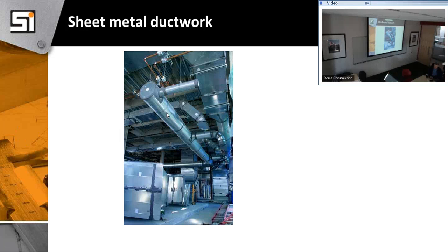The problem with rectangular duct is you get those real wide pieces of duct, and they want to waffle, so they create noise. They allow what I call breakout. Round duct is stiff, it doesn't break noise out. So if I ever went through a real noise-sensitive area, I'll use round duct because it won't allow the noise breakout. It keeps the noise in, whereas rectangular allows it to come out. That's the problem I have to deal with. But if we could do round, we prefer to do round.